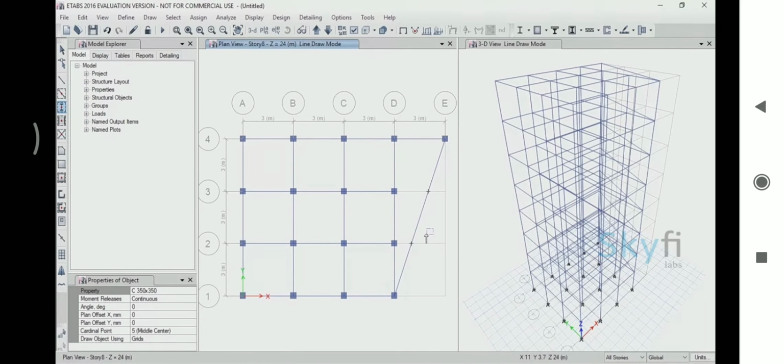Now, the columns are oriented at an angle, so you cannot place them directly. In the Column Properties box, you will find an option for angle in degrees. The angle you had noted was 71 degrees and 33 minutes, which is roughly equal to 71.5 degrees, in decimals. Give the value 71.5, in the space for angle, and press Enter on your keyboard, to store the value. You can now click on the 2 reference points, to place the oriented columns in them.